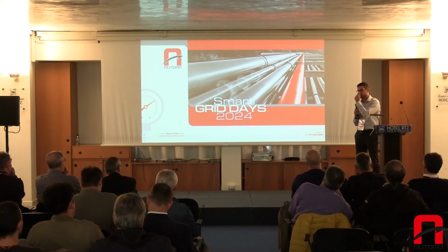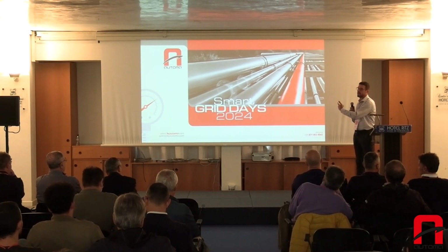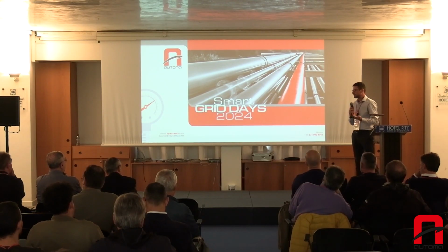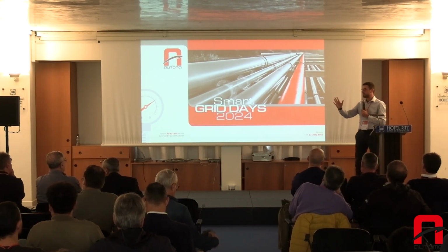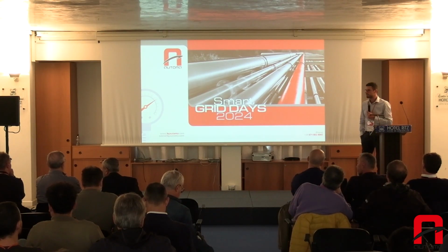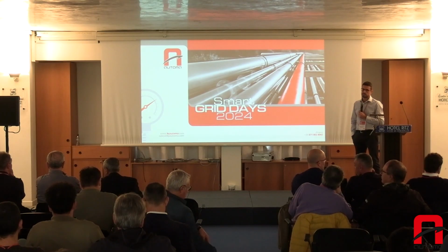Much depends on the anodes that you apply. The cost depends on the number of anodes. If you apply 4 anodes per square meter, it will cost more. If you apply 2 or 3, that will be different. And also the blades. I mean, if you cover the surface entirely, that costs more. Normally, it's 80 to 120 euros per square meter, just to give you a general indication.